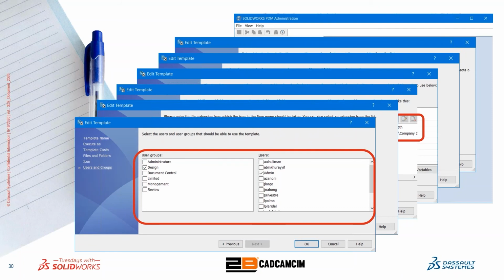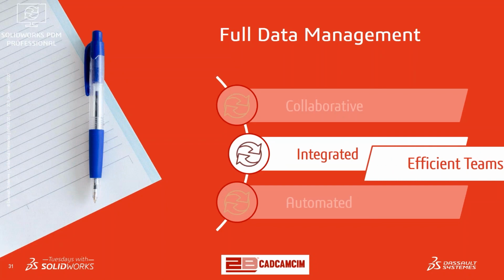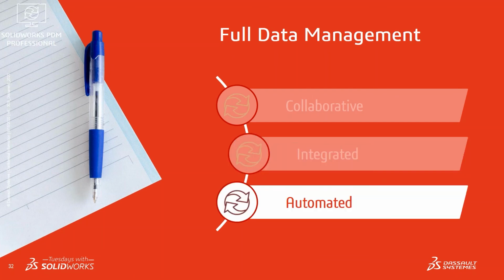just that easy. Okay, we have seen how easy it is to use and set up any ECO template inside SOLIDWORKS PDM and use the Microsoft product add-ins altogether to achieve seamless workflow associativity. The third and last portion today is the automation tools introduced by SOLIDWORKS PDM Professional to eliminate the repeated and tedious tasks that users have to do in each and every project, like generating PDFs, incrementing revisions, and approval signatures.